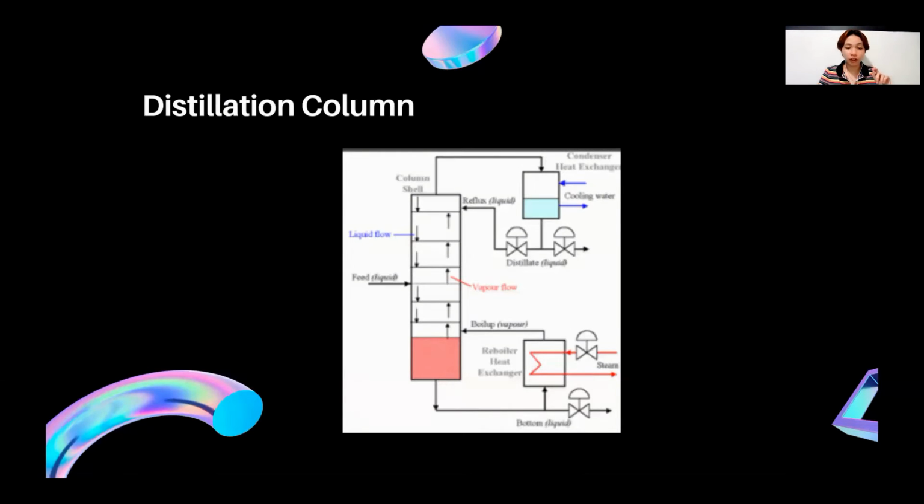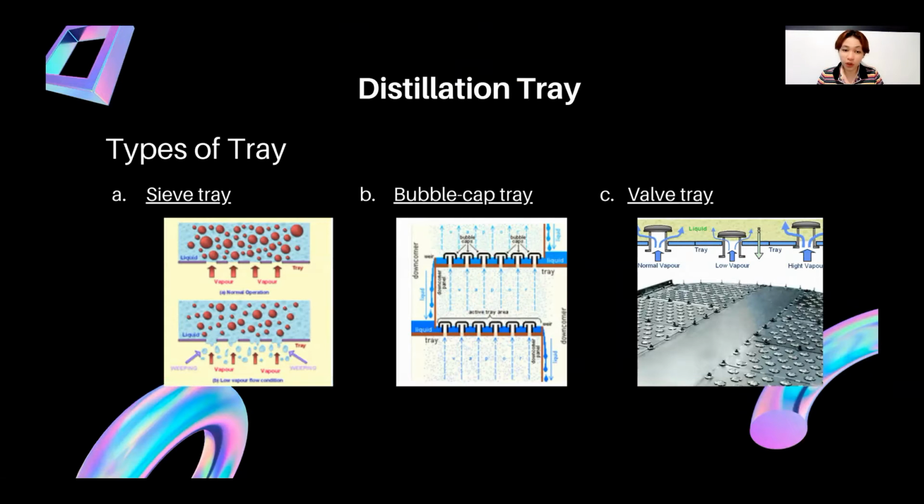So in a distillation column, we have distillation trays. A tray essentially acts as a mini column, each accomplishing a fraction of the separation task. From this, we can deduce that the more trays there are, the better the degree of separation, and that overall separation efficiency will depend significantly on the design of the tray. So trays are designed to maximize vapor-liquid contact by considering the liquid distribution and vapor distribution on the tray. This is better because vapor-liquid contact means better separation at each tray,